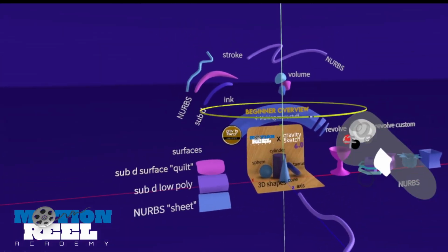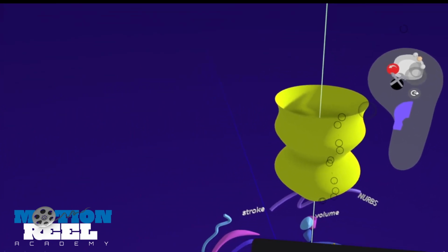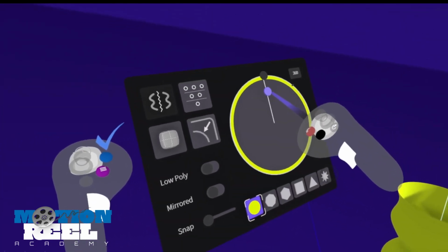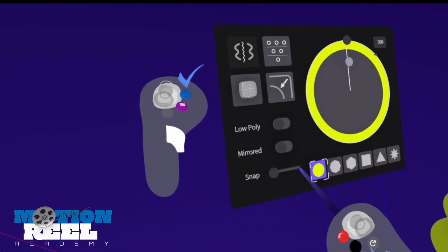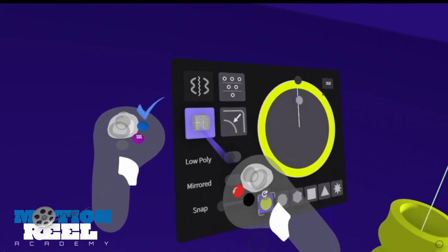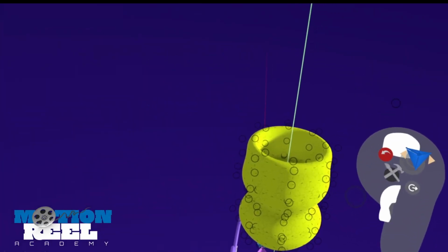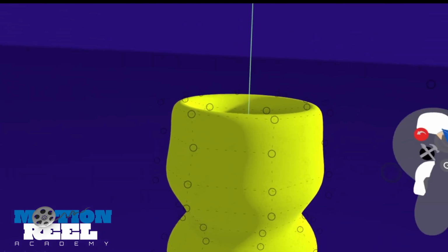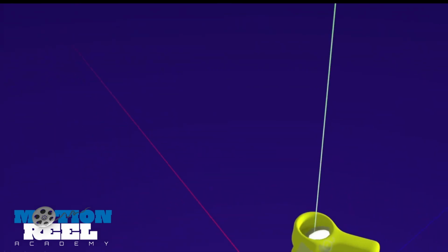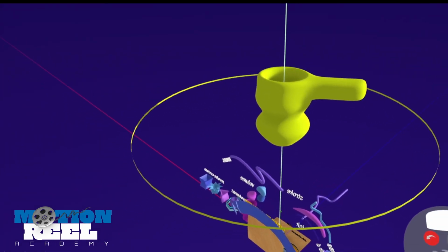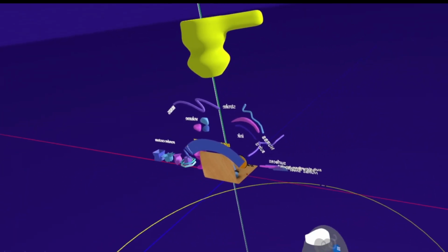Now we'll take a look at the options for the revolve tool. Let's make a revolve and put it in edit mode. Now, using this, I can change the thickness of this. We've already covered these, but here you can, of course, turn it into a Sub D object from this point and continue to work on it. All the Sub D is now already done for you, and now you can just go in and start to extrude stuff and build more complex shapes from your revolves. That's basically it for all the drawing tools and all of their options.